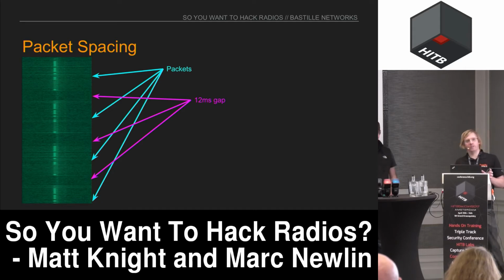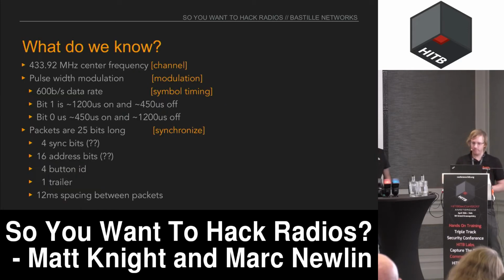And another thing that we have to consider is the packet spacing. When you hold down a button on the remote, it sends these same packets over and over again. So it'll send a packet, wait 12 milliseconds, and then send the packet again. And it will just keep doing this as long as you hold down the button. The reason is that there's no way for the LED strip itself to reply to the remote. So in order to make sure that the commands are received, it just spams them continuously.